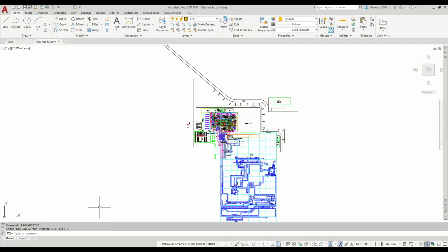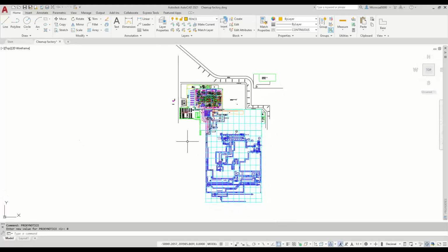Okay, right. So let's have this drawing file here. First of all, if I get a drawing file in, I need to know what's going on in here. So one of the first things I'll do is run through a purge on this file. It runs from a dialog box. Now I'm in AutoCAD 2021 here, but it works in AutoCAD LT and the full AutoCAD.